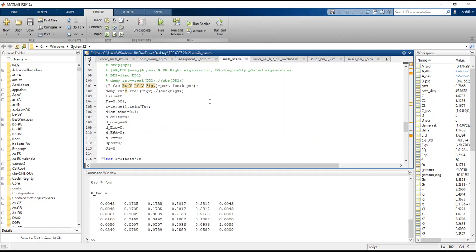In some literature, you will find that modes are used more in the mechanical domain, but in the electrical domain, they are probably satisfied with eigenvalues. In the mechanical domain, in vibration dynamics or any other kind of dynamic study, they probably use the term modes, M-O-D-E-S. And an associated term is mode shapes. So modes and mode shapes come together, and they are also linked with this same participation factor, because modes and mode shapes are again related to the eigenvalues and eigenvectors.